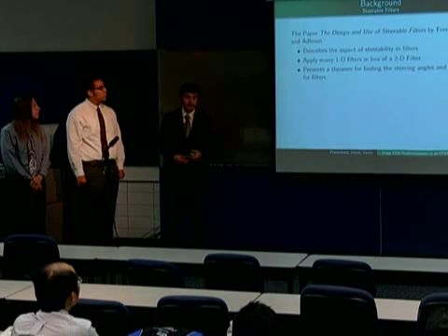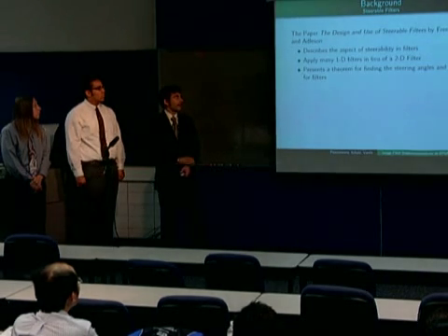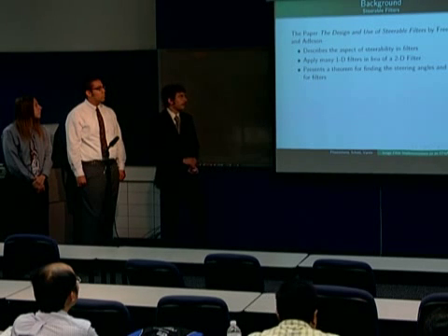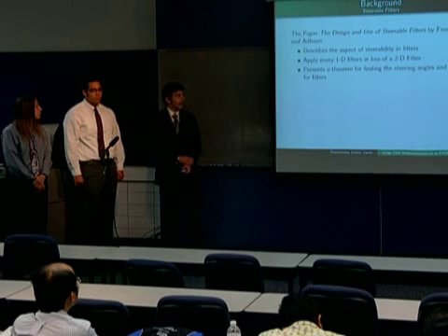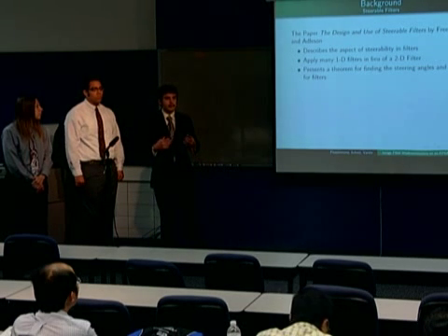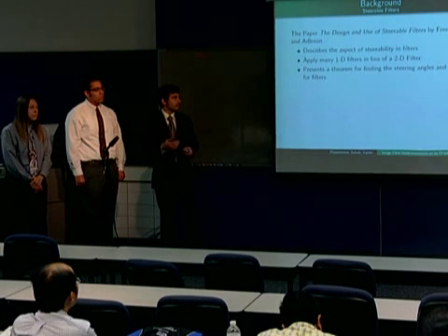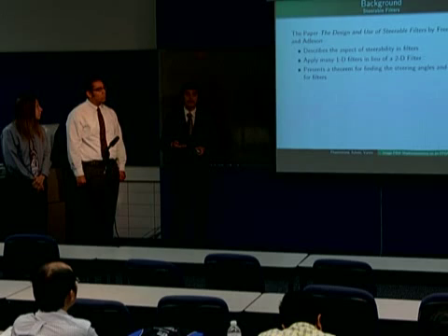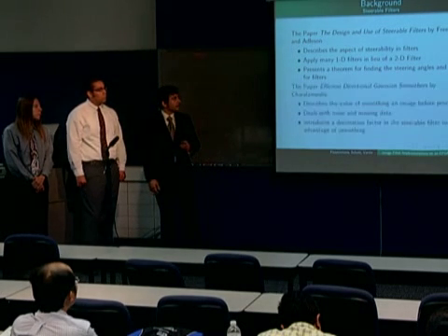So the two main papers that we based a lot of our research on, I mean, there was a lot more in the literature search, were The Design and Use of Steerable Filters by Freeman and Adelson. And it's the first paper to really introduce steerability in filters. It's breaking up directional filters into linear separable basis filters that you can apply at multiple angles. And it actually presents a theorem for finding the steering angles for these basis filters.